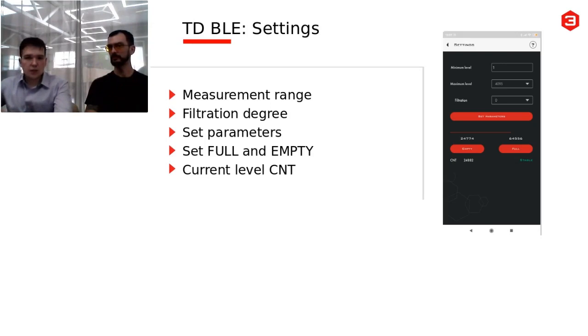And in the settings menu, you actually can calibrate the sensor. You fill it with fuel, either by inverting it and pouring the fuel inside the tubes, or by putting the sensor into a tank, or say a tube that keeps fuel inside. It's really about filling the sensor from down to top to the drainage holes. Then you click the full.